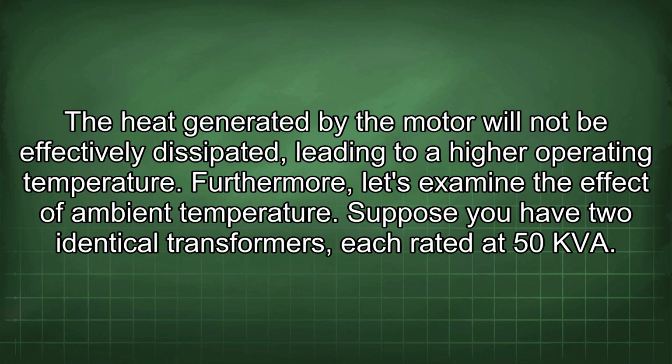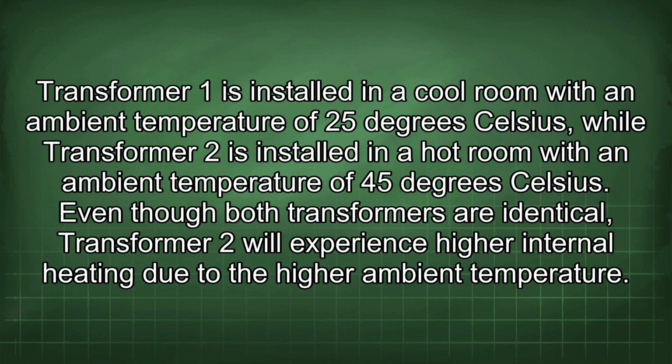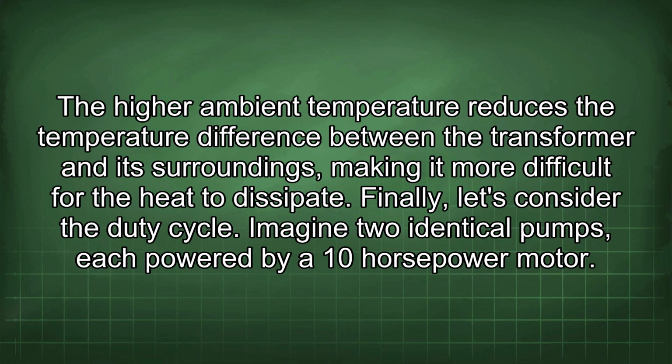Furthermore, let's examine the effect of ambient temperature. Suppose you have two identical transformers, each rated at 50 kVA. Transformer 1 is installed in a cool room with an ambient temperature of 25 degrees Celsius, while Transformer 2 is installed in a hot room with an ambient temperature of 45 degrees Celsius. Even though both transformers are identical, Transformer 2 will experience higher internal heating due to the higher ambient temperature. The higher ambient temperature reduces the temperature difference between the transformer and its surroundings, making it more difficult for the heat to dissipate.